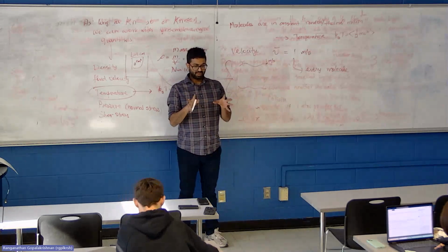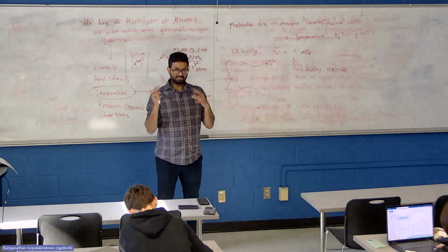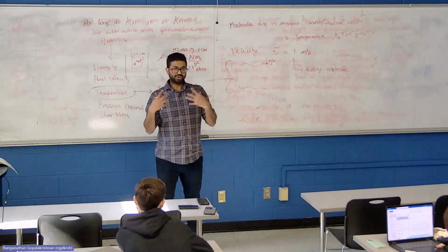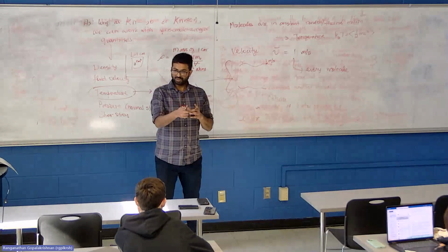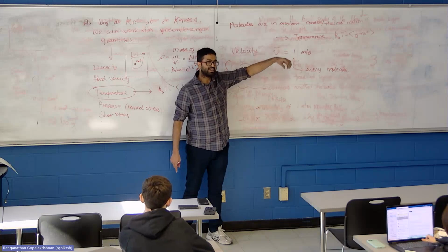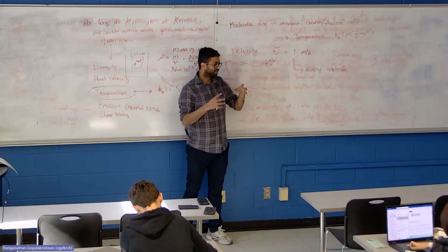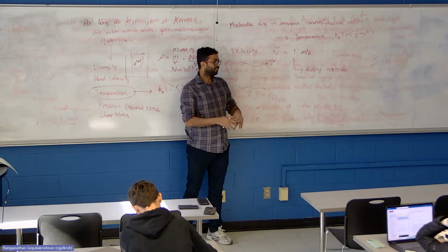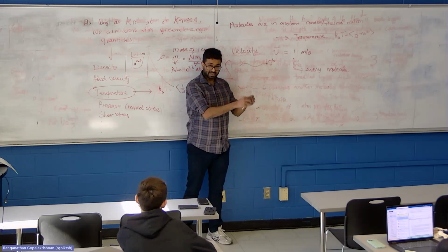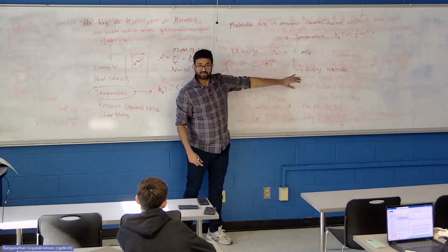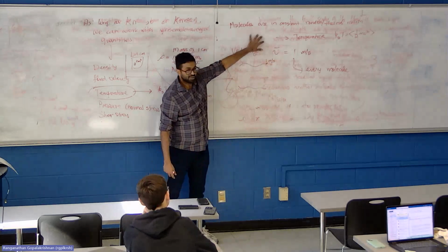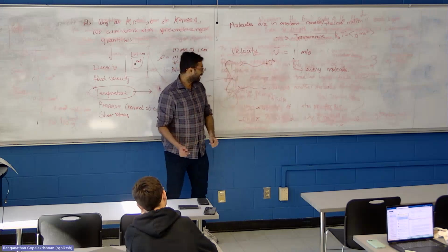So think about it this way. We are all randomly moving, assuming we are like the atoms. But if the room itself is drifting slowly in a particular direction, we all have both our own individual random velocities and a collective frame of reference velocity. That is what this 1 meter per second is. This is the ensemble average of all the molecules, so that their random components cancel out, and what remains is the systematic velocity. So whenever you say the fluid at a given point has such and such velocity, it means all the molecules at that point are drifting in a particular direction at that velocity. That's what velocity means. Okay, it's the difference between there is always motion, but there is not always collective motion.